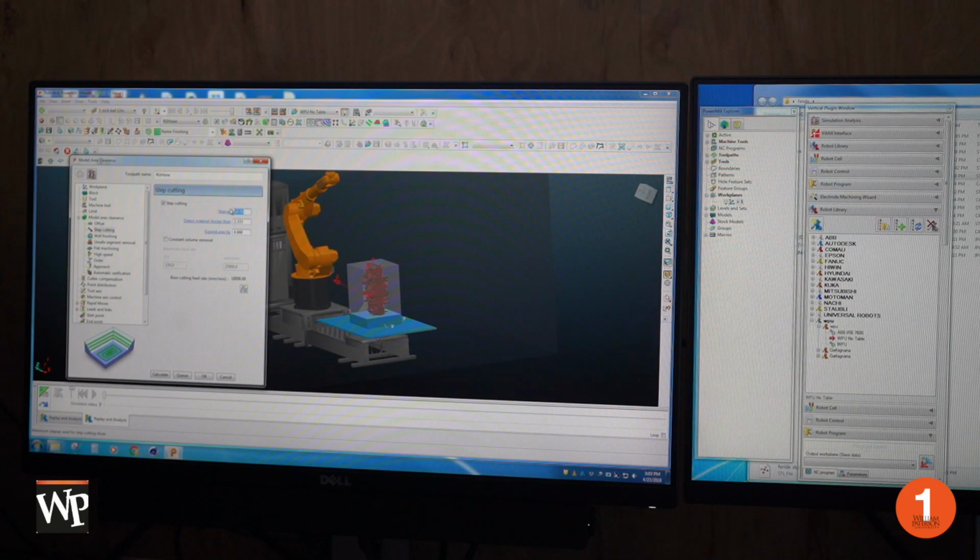So rather than have that, we're going to change this to 7 millimeters. And so then it steps down 75 on each cut. It does a full layer. And then when it gets close to the model, it comes up every 7 millimeters to keep from having big angles when we do our finishing.